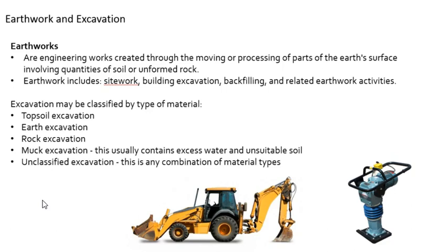The benefit to the owner is that an unclassified excavation puts all the risk onto the contractor. However, when a contractor takes on such risk, of course, they charge for it. They don't know if it's going to be an easy excavation or if they're going to come across rock. So they have to plan for the worst case scenario while, of course, producing a competitive bid.